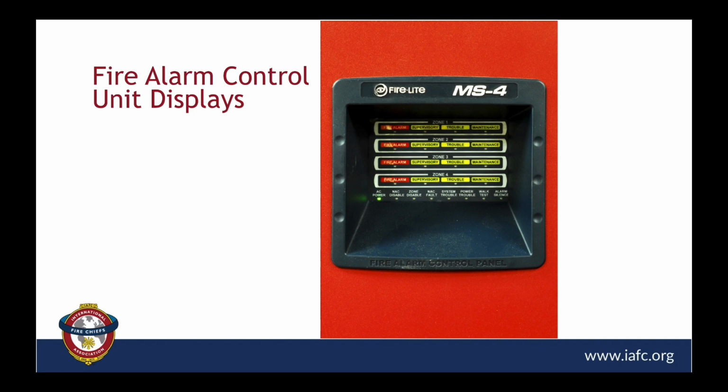And this is what you're going to see from the outside. And you're going to see now just lights that light up here. You're going to see zone 1, and then you can see this one is red for fire alarm, supervisory, trouble, and maintenance. I'm going to talk about that in a second. But now you can see this particular system has 4 zones. That could be floors 1 through 4. It could be floors 1 and 2 with a water flow on each floor. It could be a couple of different configurations. That's why you usually need some form of a chart or a zone map next to this so that you know what those zones mean.